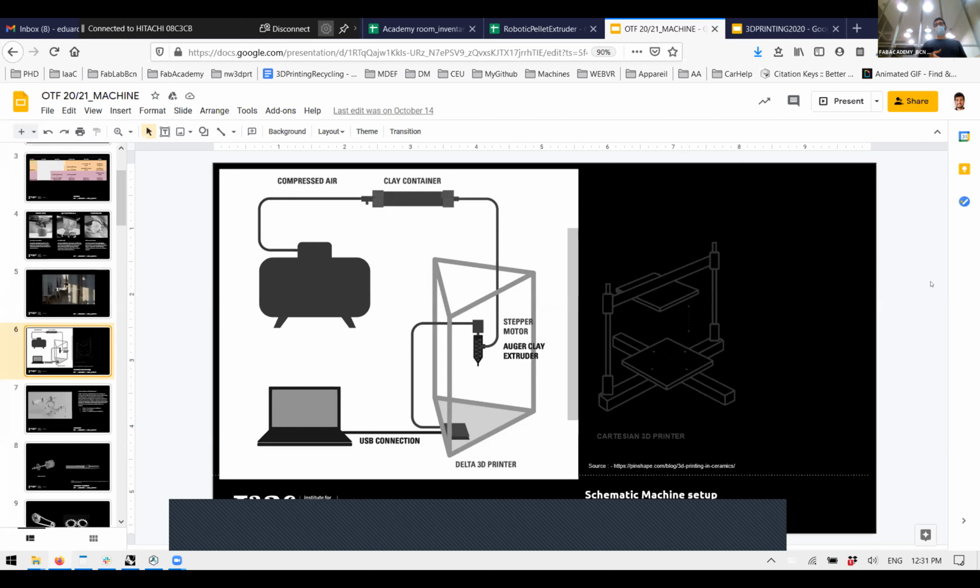The drier the mixture, the more height you can reach because it doesn't collapse, because the material is stronger. But also you have more problems for extrusion. For example, in that one, they use a lot of pressure because you cannot print more than 30 centimeters if the mixture is not really, really dry. In this scale, you can print bases like this with double the liquidness of the big extruder, just because of the different scale.